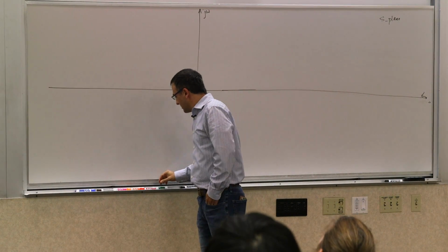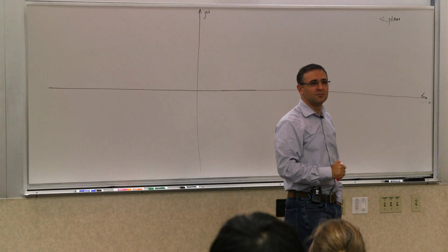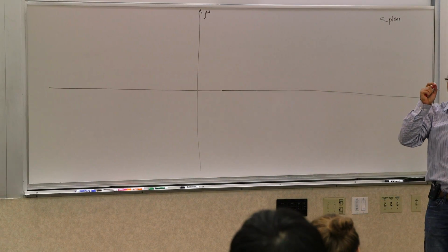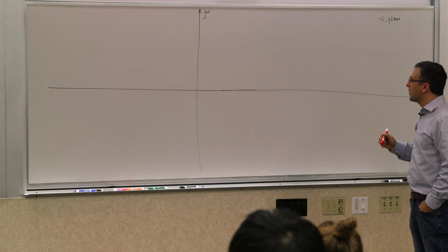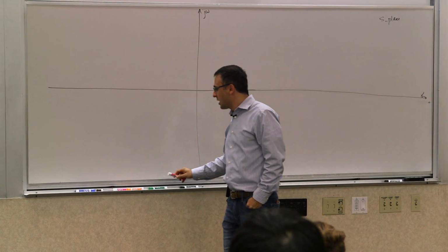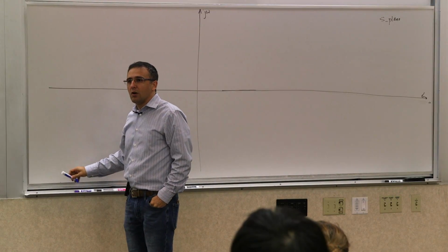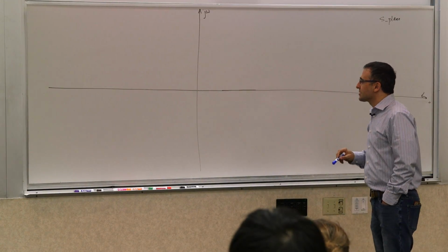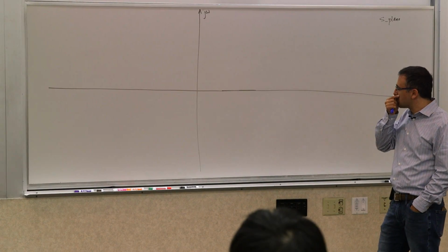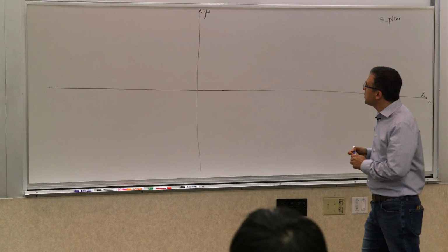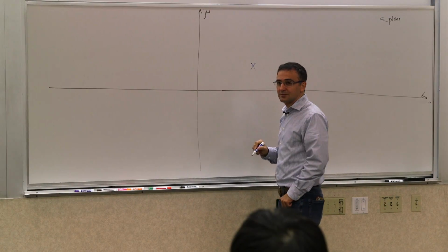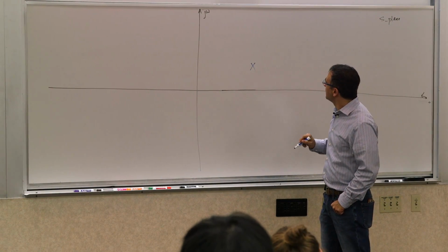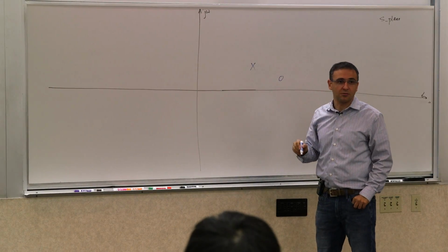Okay. So now let's start with something very simple. What we are trying to do is to find the impulse response. So what we are showing is the impulse response of a system with certain poles and certain zeros, starting with the poles first, and then we'll see how the zeros get into the equation. By the way, we show the poles with x's. So if I put an x here, it means that the system has a pole here. And we show the zeros with O's, like zeros.